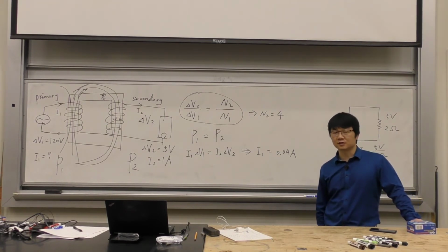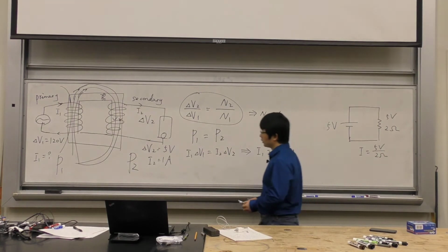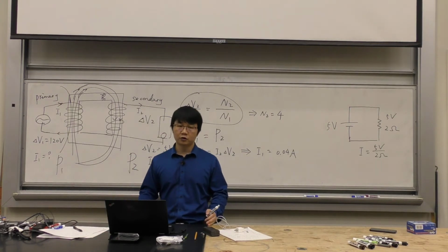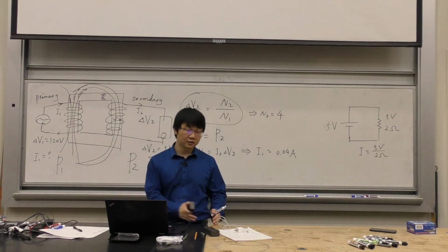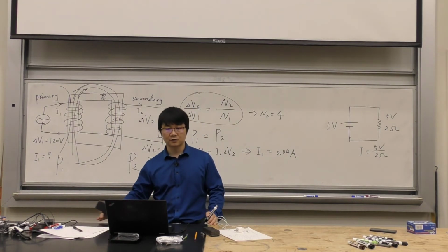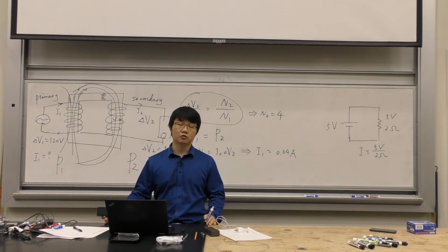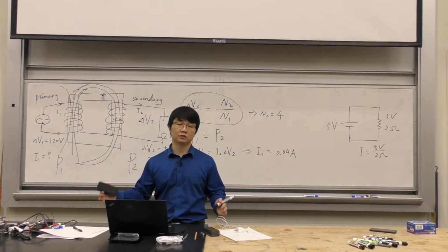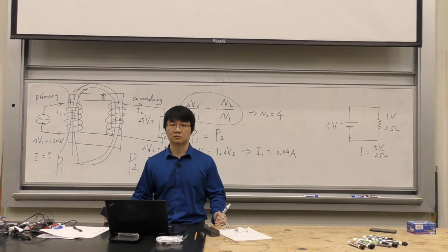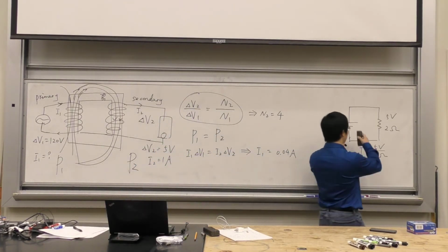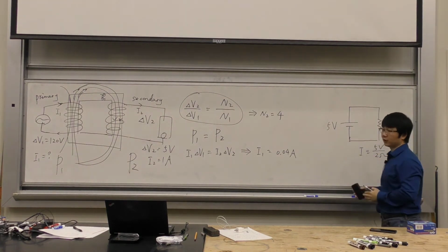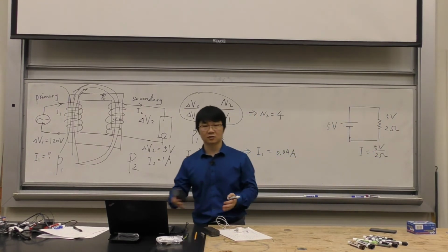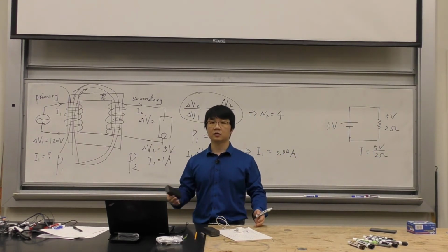But transmission lines are different, because they deliver power from the power station to a city. If the distance is a few hundred miles, you're going to have transmission lines of a few hundred miles. You can't just ignore their resistance, because it's not like a very short copper wire, whose resistance is too small to calculate. With conducting wire a few hundred miles long, you cannot ignore the resistance.